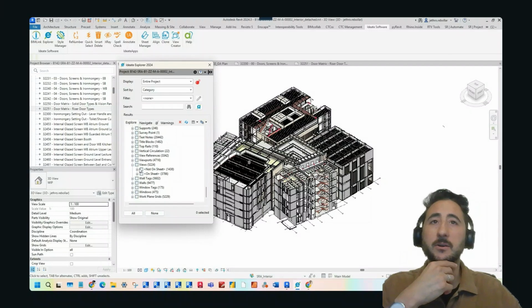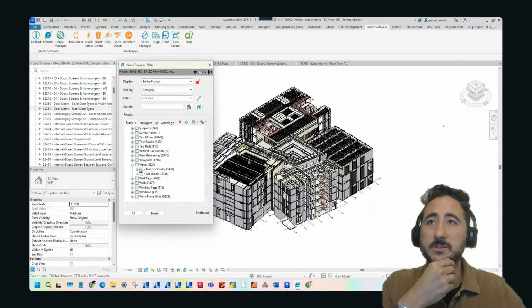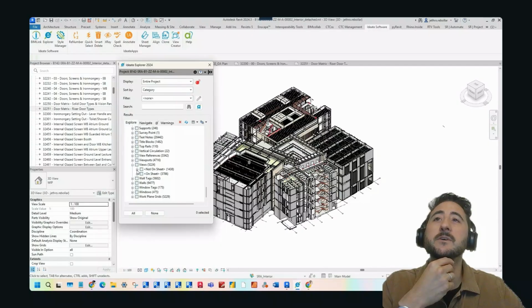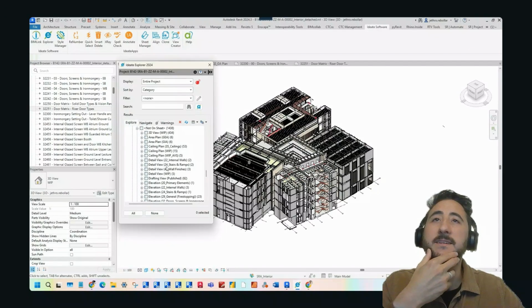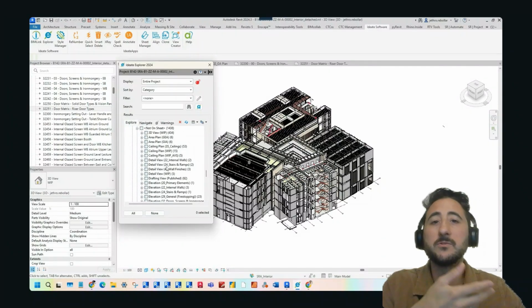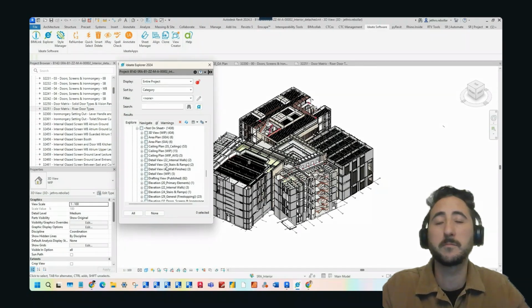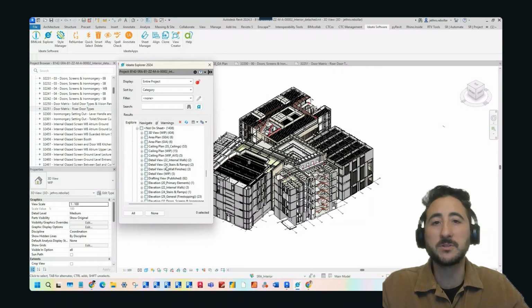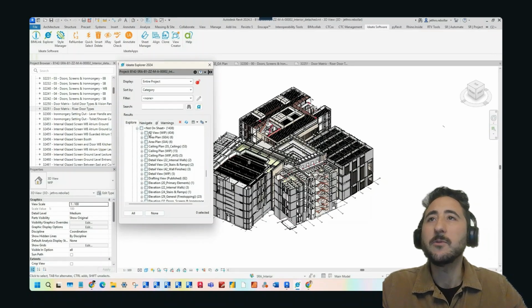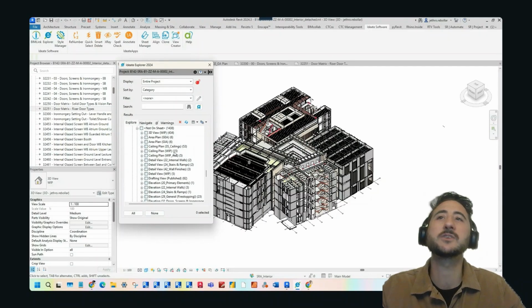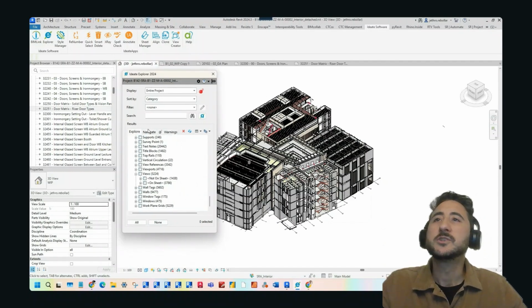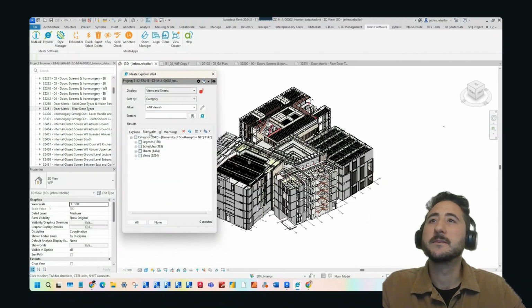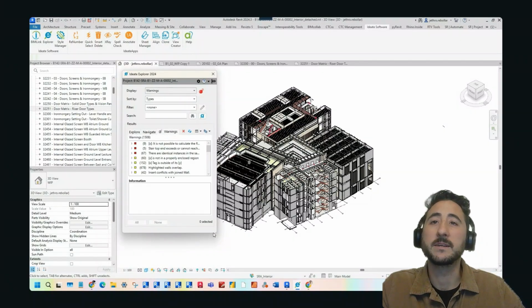So as a BIM coordinator or someone that's running quality assurance, quality control on the project, I can already determine that there's a third, if not more, of these views that need to get taken a look at, right? Because if you have views that aren't being used for documentation, that aren't being put on sheets, then it bloats the model. And I can see already that there's a bunch that are work in progress views that are not on sheets. So these are ripe for deletion, right? At least review.